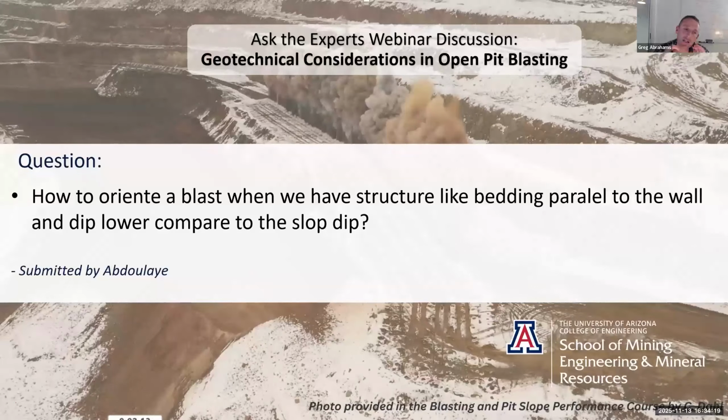Yeah, I think that cohesion is a great point. We were having an incipient foliation to deal with. We actually figured out we could undercut it and it would stay there if we were nice to it. And then there were other times where we just had to sort of embrace this thing and put in some stab rows and break it off ahead of time so it would come down to the shovel. And that was the best option there.